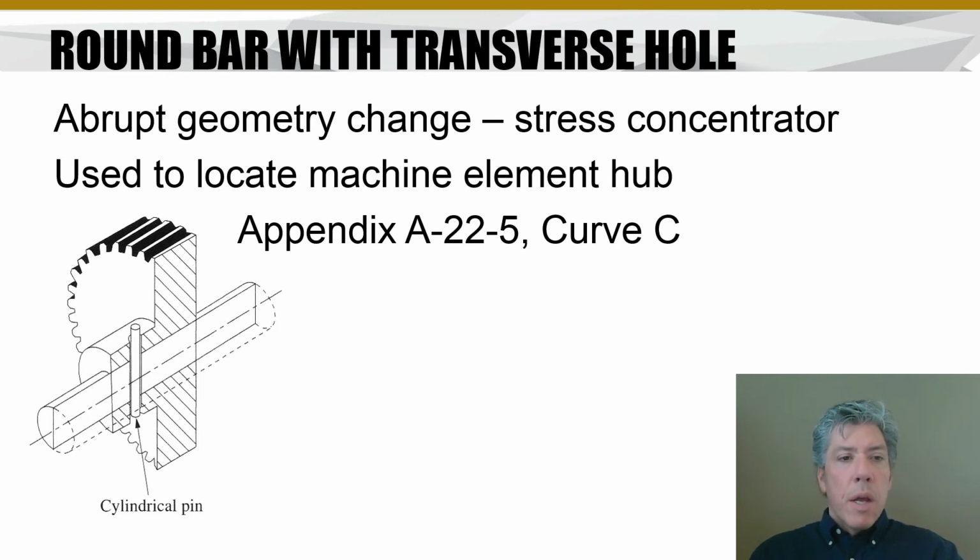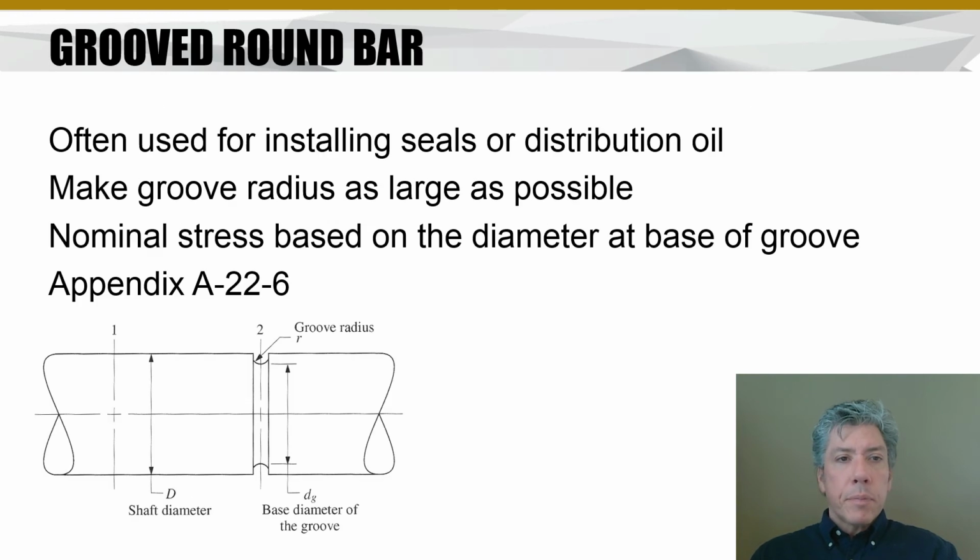So this is used, and of course it can be used too for parts that can be disassembled and reassembled and parts replaced. It can be used for interchangeable assemblies as well. You just have to drill the hole more precisely, and that has been done. That's fairly common as well. But the point is that this causes stress concentration in the shaft, and we have stress concentration factors for it.